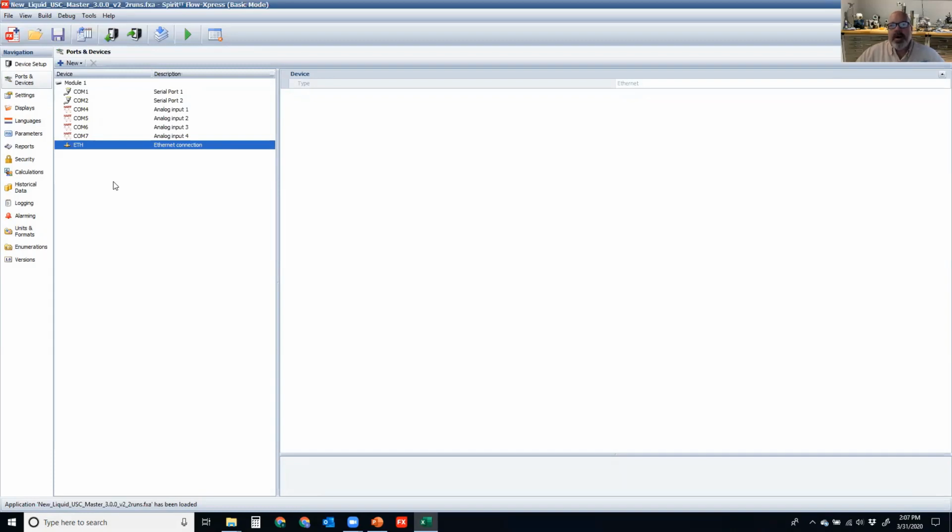So if I need to talk Modbus, I can make it look like other Flow computers that may be out there, or I can just select our generic tag list where we have our tags mapped out to specific Modbus registers. And we're able to print that out and display those registers. So when you're setting up the FlowX, you can give that to a PLC or DCS or SCADA engineer, and they'll be able to pick the appropriate Modbus registers.